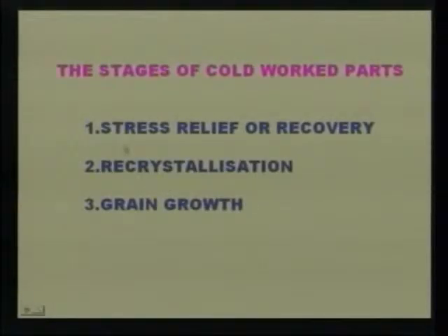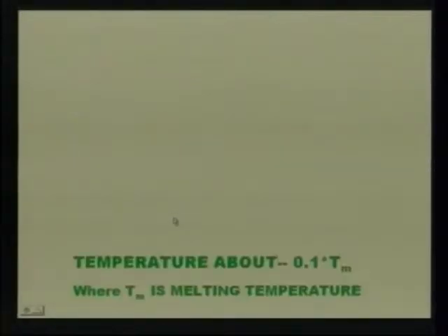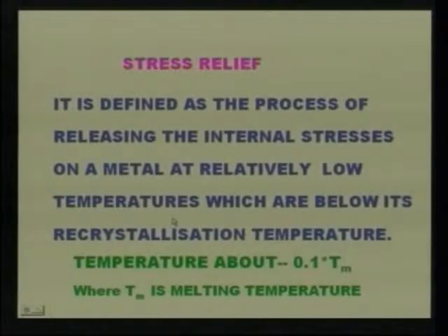Now these are the 3 stages. One is stress relief or recovery, the second stage is recrystallization, and the third stage is grain growth. Now let us see the stress relief. What is stress relief? It is defined as the process of releasing the internal stresses on a metal at relatively low temperature, which is below its recrystallization temperature.